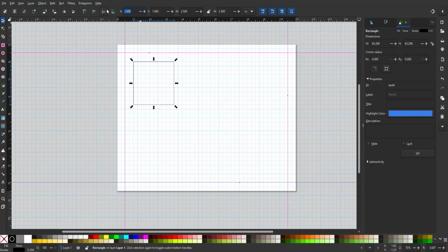So if I make this X 4 inches, the top left-hand corner is going to pop over to the 4-inch line on our ruler. Ba-bam. And you can see up here the 4-inch line. So that's a way to be really precise, what you want when you're manufacturing things. And it's just simpler than trying to scoot it around and guesstimate. I like to be really precise. That's my architecture background.